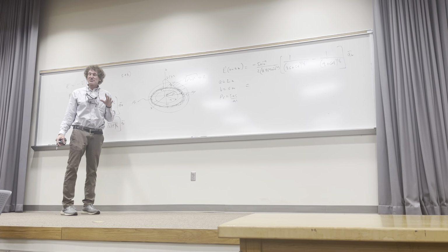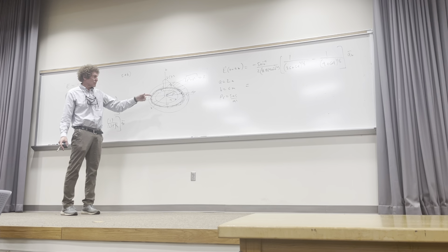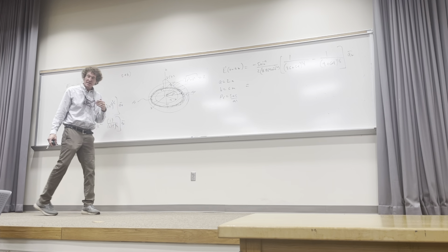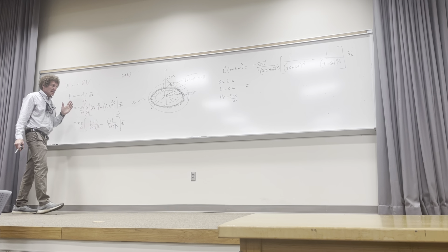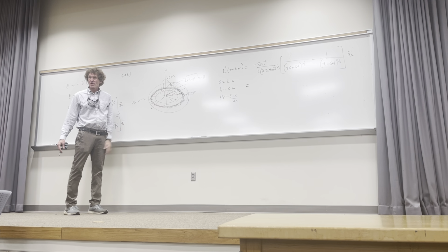It'll change the answer. So I'm going to tell you, just memorizing formulas is not the wisest thing when it comes to something like this, because if rho s is a function of position, of radial distance, nothing I've done after that point applies, except to get the differential voltage here at a given radial distance rho. Then that would be 2 pi rho, the circumference, times rho s, but rho s could be a function of rho. You all with me?